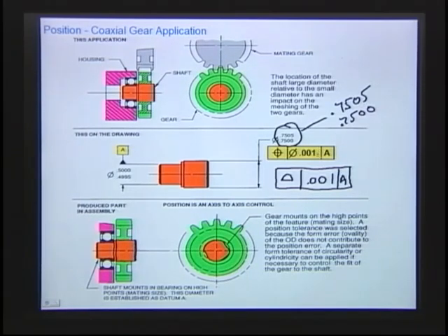And then the location is another problem. You see what profile would do? Profile just gives you a boundary, an inner boundary and an outer boundary, and the surface has to fall inside of it. So it includes the size, it includes the location, everything in this one lump sum. So to me, this would not be appropriate for profile.